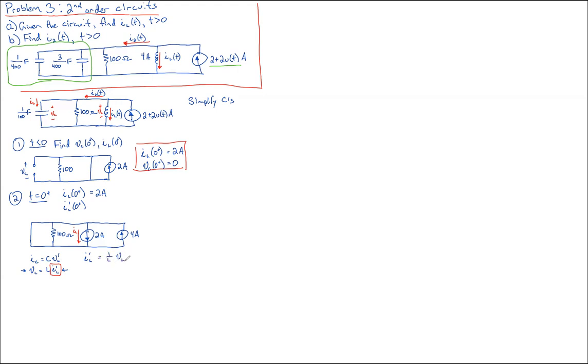So now we need to find out what our V sub L is in this time region. So I drew our I sub L, and according to the passive sign convention, voltage always exits more negative than it enters. So we have to draw our V sub L like this. So now the question is, what is that V sub L? The V sub L between this node right here, which is what we want to find, and this node, well, the voltage has to be the same everywhere along the node, right?